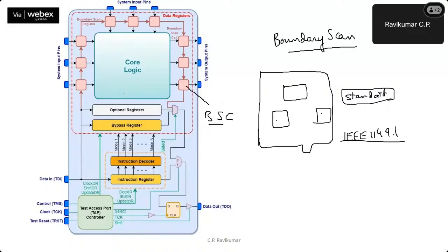But in addition to that path, that is a parallel path, we will also have a serial path like this. So these boundary scan cells will allow a test mode in which we can shift in data into these boundary scan cells. So for example, let us say these are the input pins, and let us say I wanted to simulate the jumper wire, right?